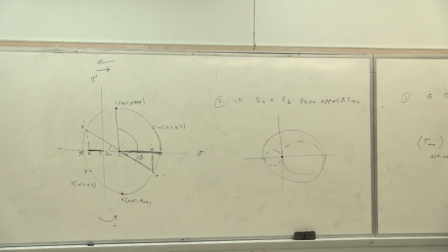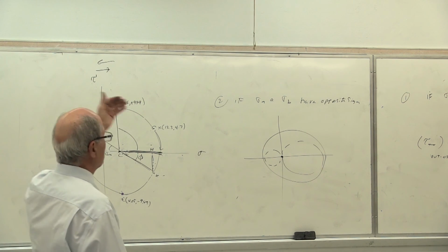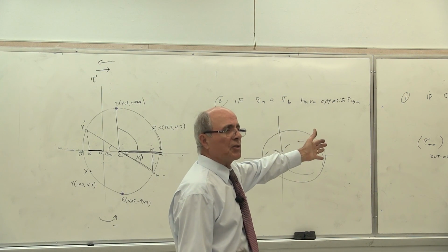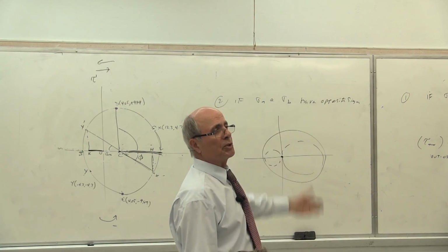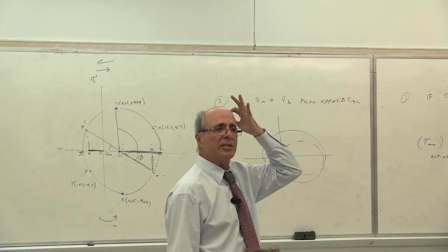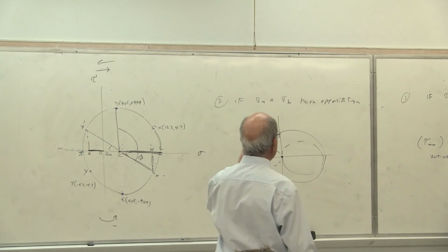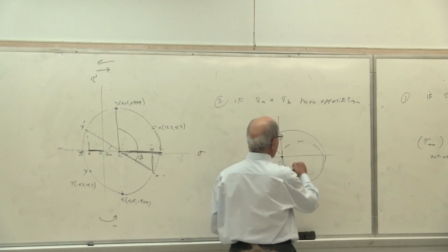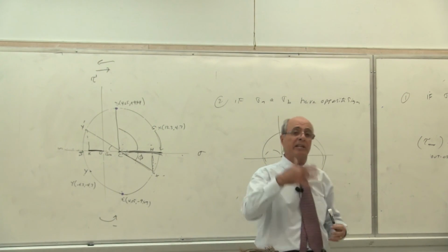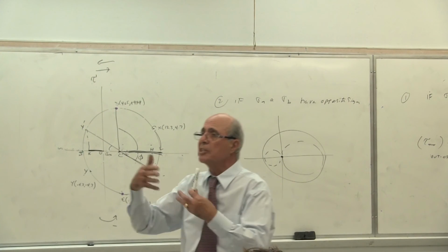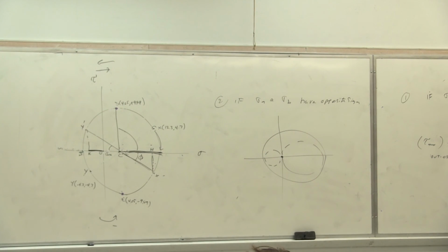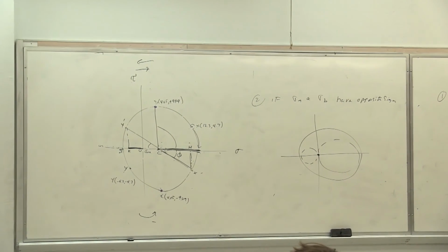So therefore, because really it's procedural, everybody see that, it's very simple. All you have to do is draw your original circle and then draw the other 2 circles according to sigma z. Is that correct or not? By doing that, you can find the radius of the larger circle, which is your absolute maximum shear. But it could be in plane, it could be out of plane, this way or this way. Everybody understand what I'm saying?